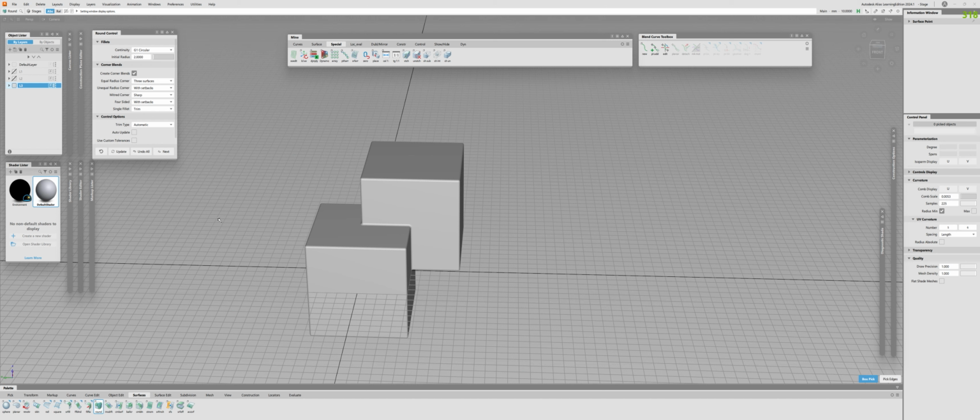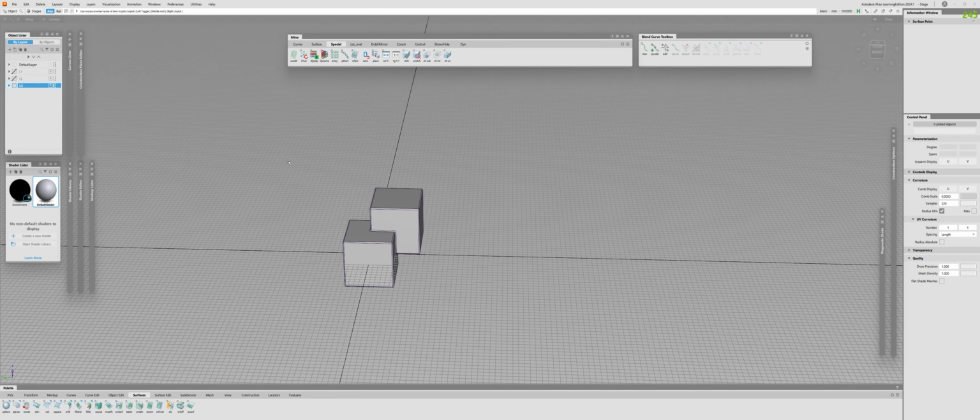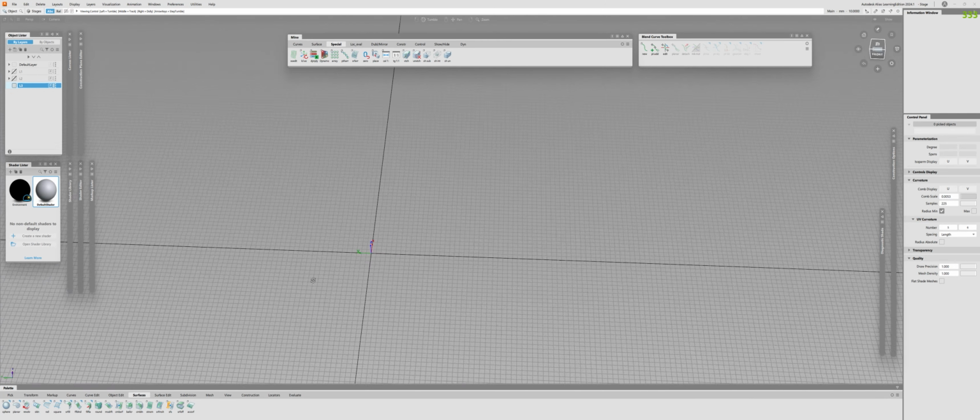Now, Boolean operations doesn't necessarily mean that you need to cut one solid body with another solid body. You can use Boolean operations with surfaces as well. But the one important thing, though, is that the surface should be stitched. Now let me show you this example as well.